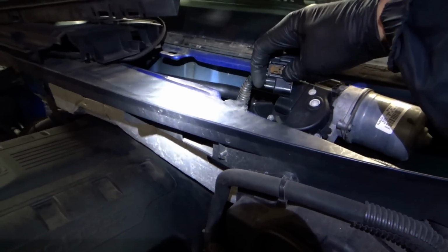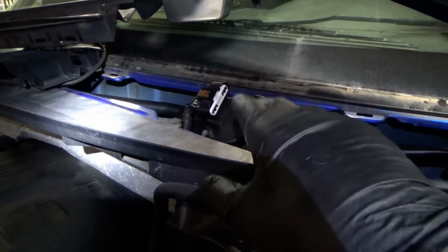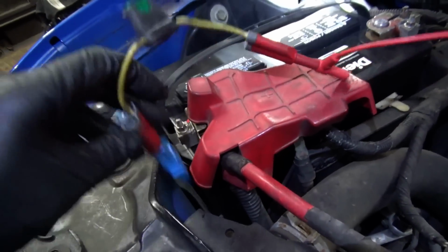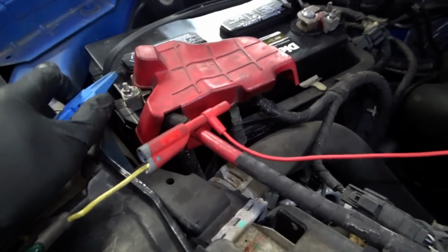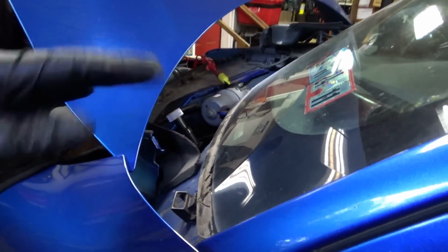So for now, let me bypass that wire. We'll just provide power here, plug everything in, make sure the wiper motor works, and then we'll chase this power circuit. Alright, here we go. So through a fuse, it's going to feed power to that circuit. You saw a little spark there. So let's see if the wiper motor works.